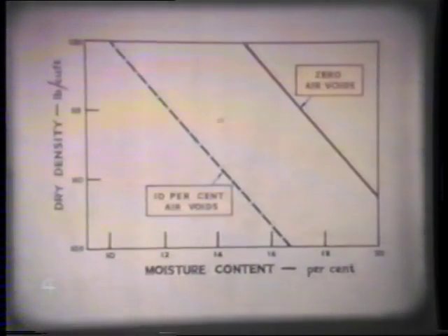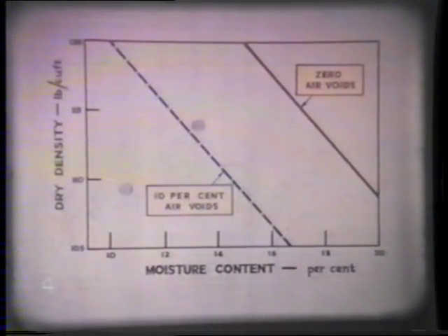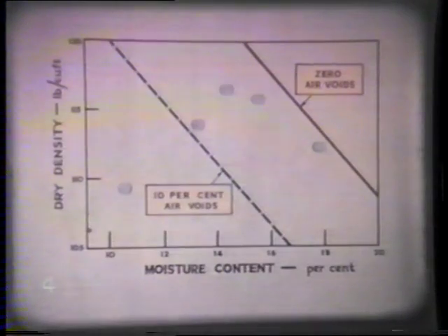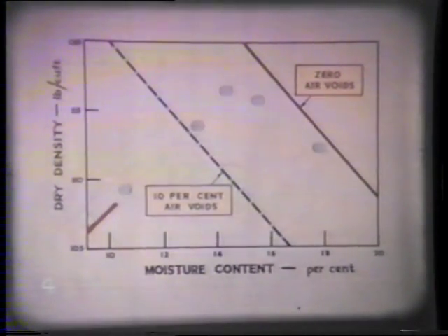The compaction procedure and the density measurements are repeated with the soil at a different moisture content or with different numbers of passes of the machine. Three main factors are studied in the tests. Firstly, the effect of the moisture content of the soil on the state of compaction obtained. This relationship shows the range of moisture content over which the machine can be usefully employed and the state of compaction which can be achieved.